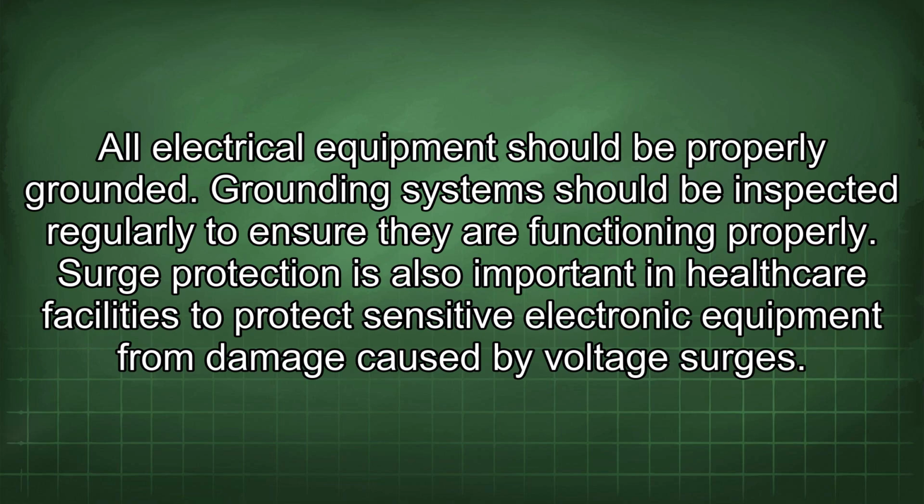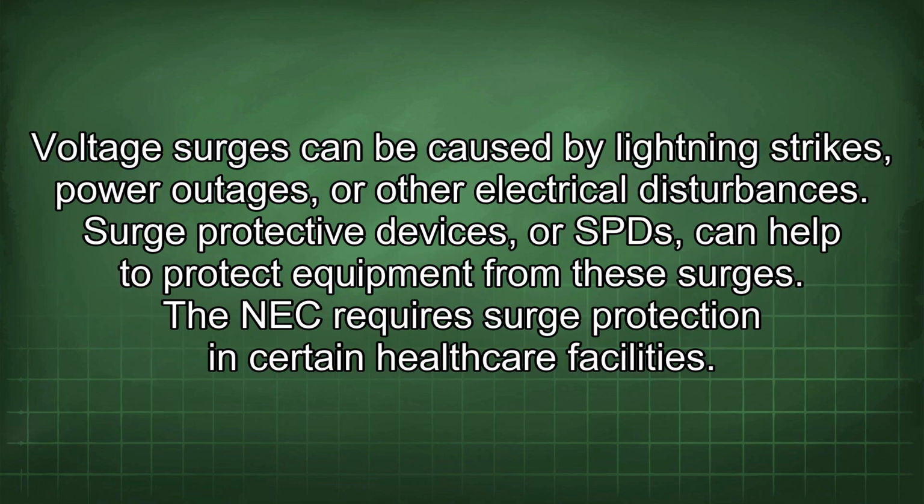Surge protection is also important in healthcare facilities to protect sensitive electronic equipment from damage caused by voltage surges. Voltage surges can be caused by lightning strikes, power outages, or other electrical disturbances. Surge protective devices, or SPDs, can help to protect equipment from these surges. The NEC requires surge protection in certain healthcare facilities.